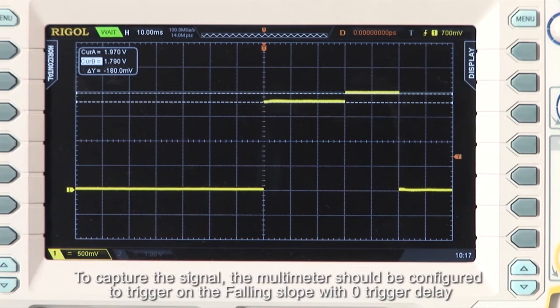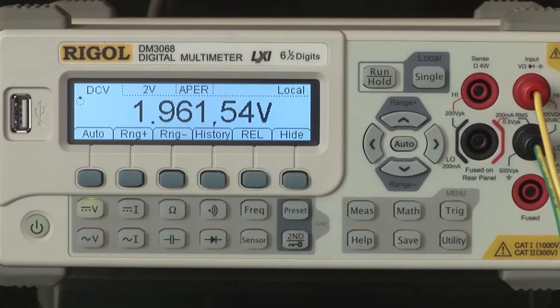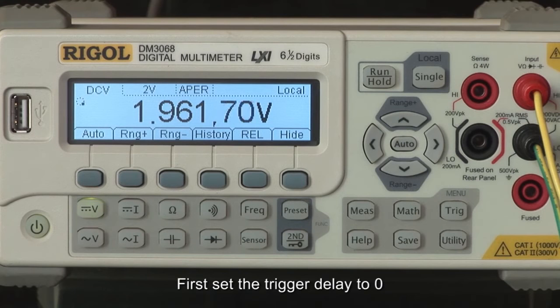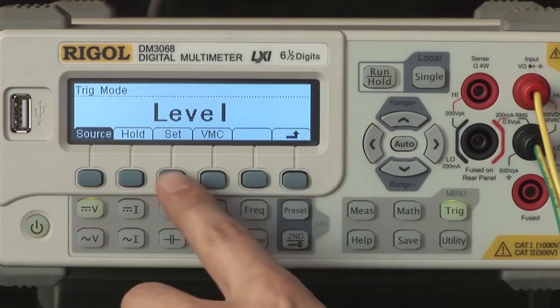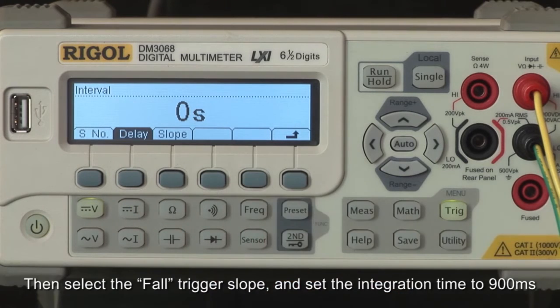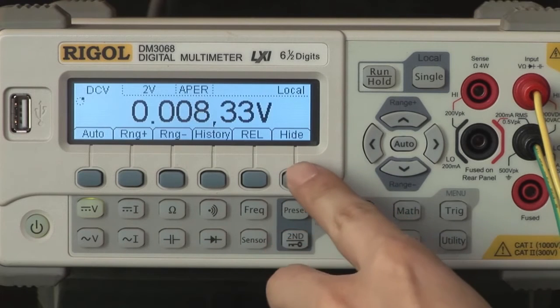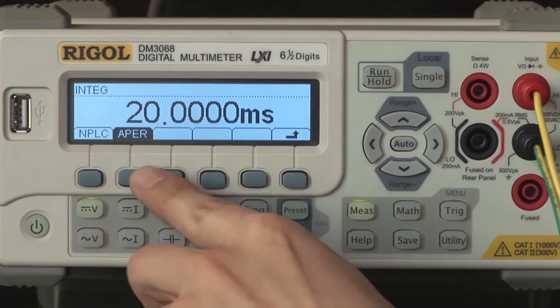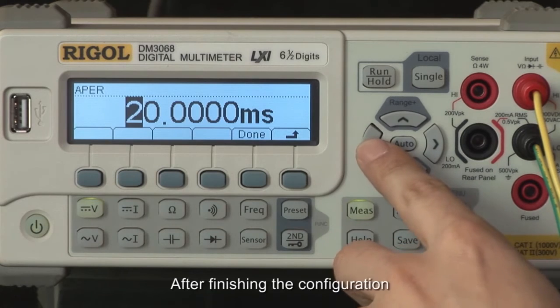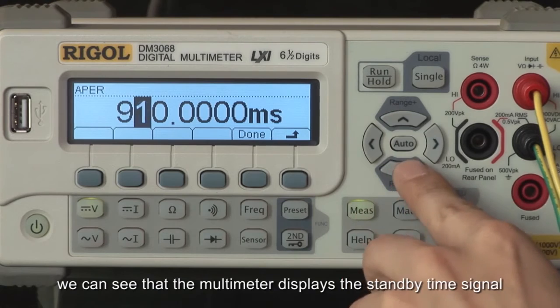To capture the signal, the multimeter should be configured to trigger on the falling slope with 0 trigger delay, and a measurement time of 900 milliseconds. First, set the trigger delay to 0. Then select the fall trigger slope, and set the integration time to 900 milliseconds. After finishing the configuration, we can see that the multimeter displays the standby time signal.